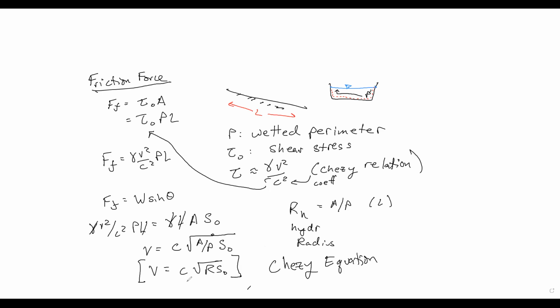It's empirical, so it's a little bit of both, right? It's fundamental where the physics kind of work out, but this coefficient, anytime you have a coefficient, you have to look it up in a table because it's calibrated based on experimental data. And therefore, we ultimately call this an empirical equation, just like the Hazen-Williams equation. So this is kind of like Hazen-Williams, except for open channel flow.